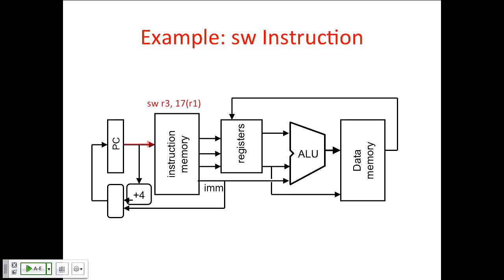So going through here, we read the instruction bits. This part is the same as before. So now we're taking the register base address, adding the immediate to it to get the address we send to data memory. But the data value now is going to come from this register file read port. The other register we read is now sent as data to the data memory to be stored into the memory. Right, so there's a set of wires carrying the values you want to store to the memory, as well as a set of wires telling you which address you want to store it at. Okay.